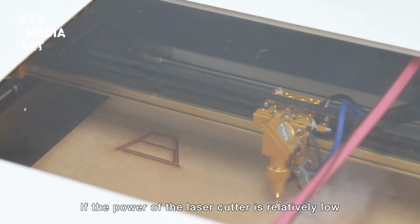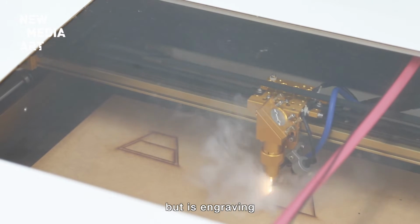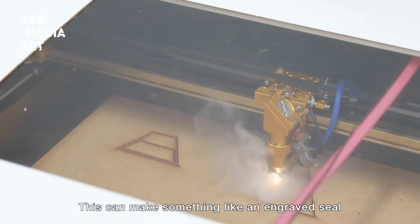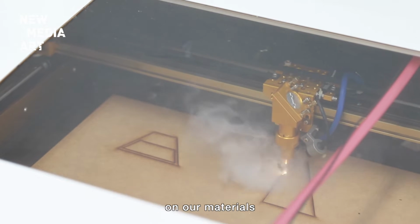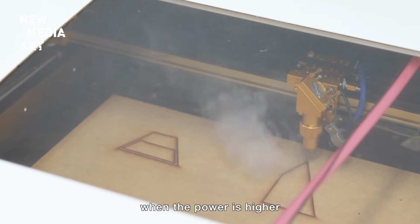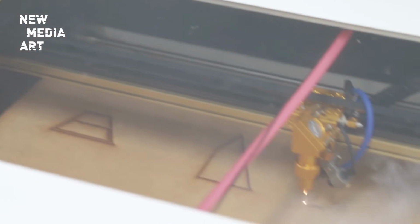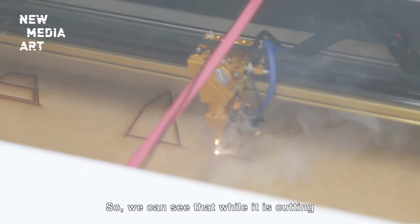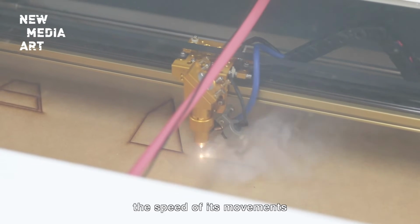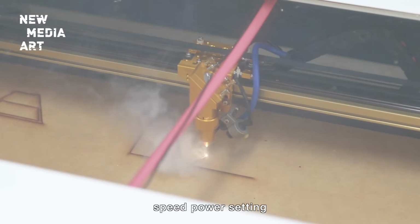If the power of the laser cutter is relatively low, it is not actually cutting, but is engraving. This can make something like an engraved seal on our materials. This sort of action, when the power is higher, becomes cutting. A cut goes all the way through. So we can see that while it is cutting, the speed of its movements actually has a certain speed power setting.